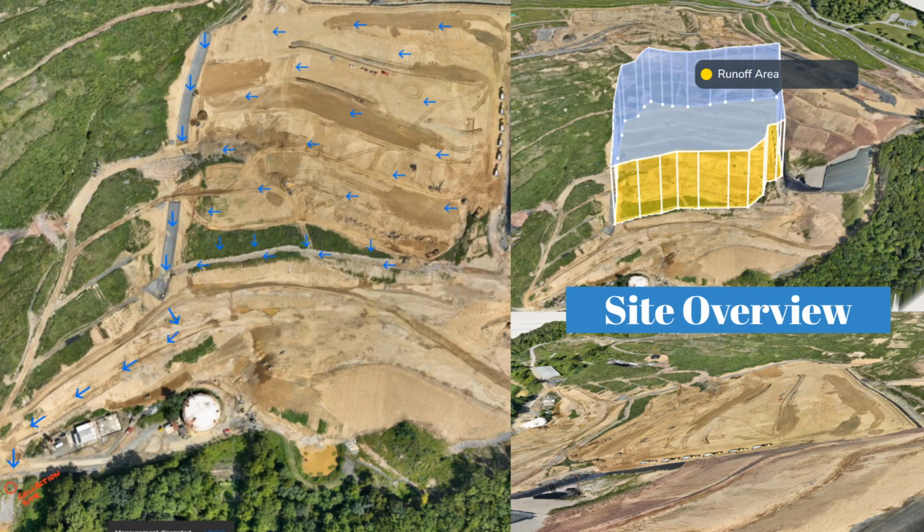Here shown on the slide are pictures of the landfill or site that we took the water from. Down in the bottom corner, circled in red, is where we collected the stormwater runoff through a 60-inch concrete pipe that fed into a detention basin. The blue arrows are the way the water flows down the site. It flows into a downshoot, which is then directed into the 60-inch concrete pipe.